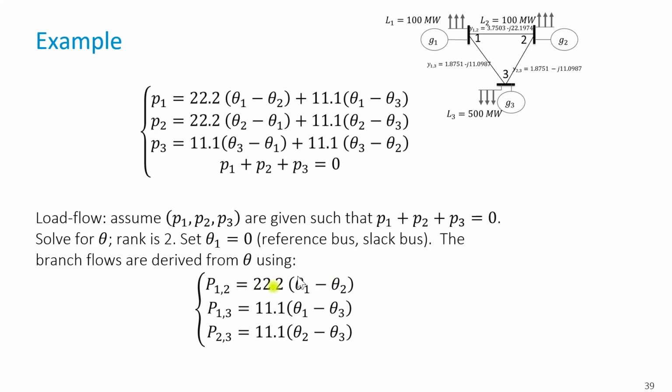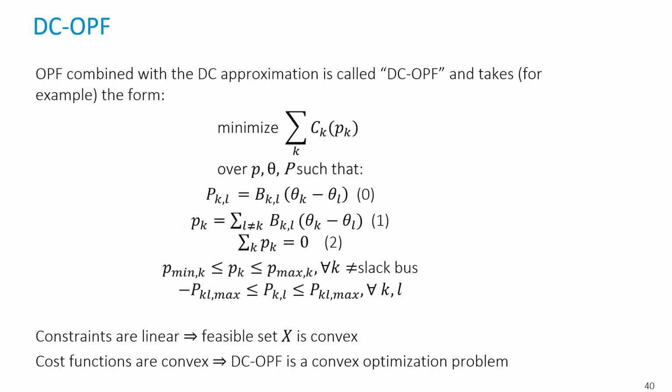Of course, here we're not able to compute the line current because we've lost the reactive part. So we're only able to compute the power that flows. This is why very often we give apparent power limits that are even interpreted here as active power limits, when we do only the DC approximation. That's the only thing we're able to do.